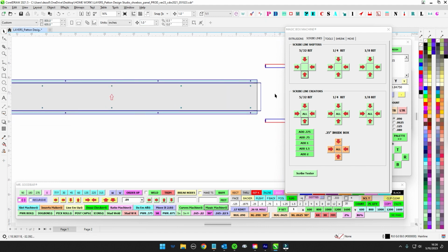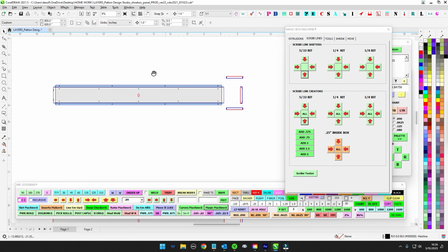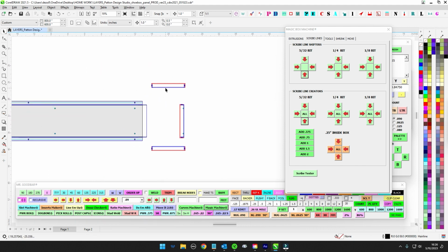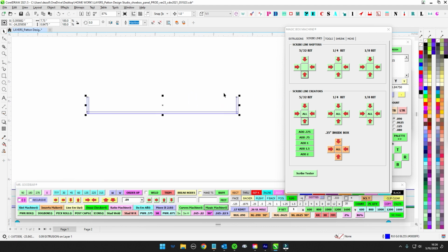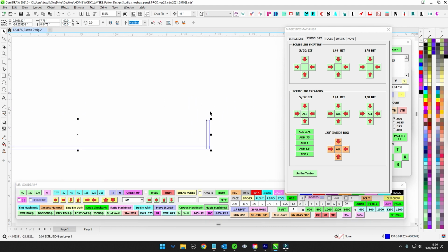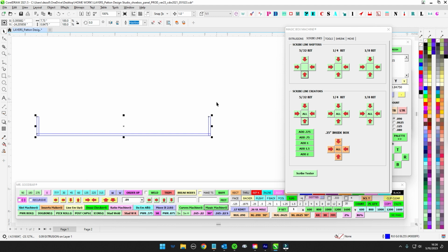So there you go. Now, here's another issue that you have to learn if you're going to do this, is that when you bend and create a C channel like this, the part you clamp will grow 1/16 of an inch. That's just how it is.